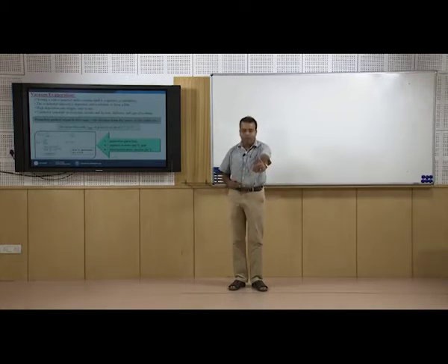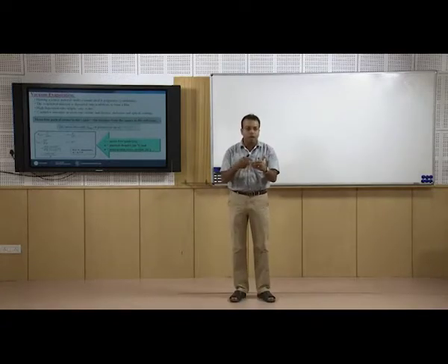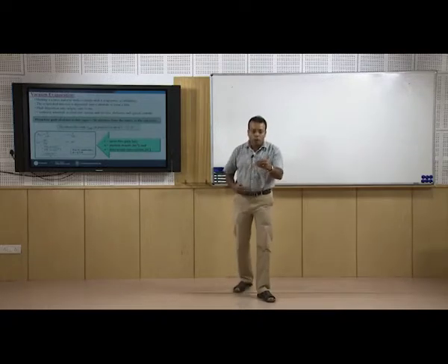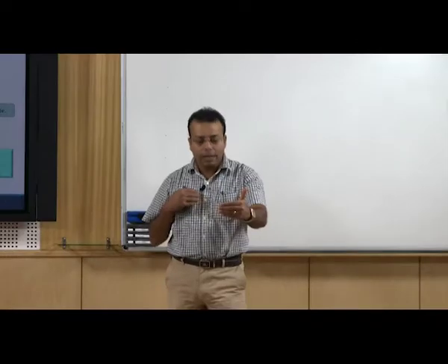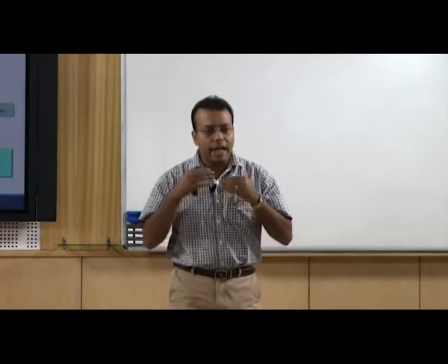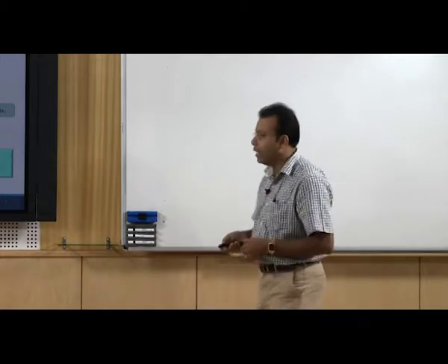My target may be 1 foot from my standing position, but if my mean free path is less than that, what will happen? I will not directly touch the substrate material. So my mean free path has to be more than the distance between the source and the substrate, and only then can I go and directly hit the substrate and deposit onto the substrate material.